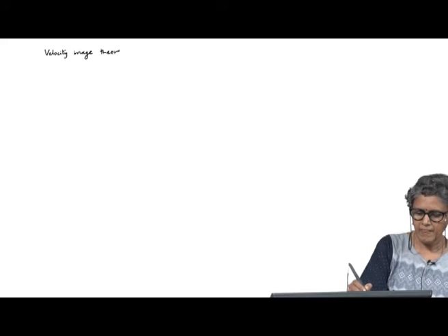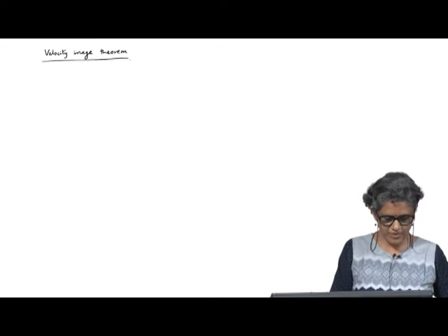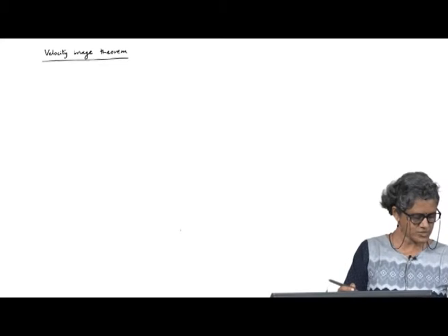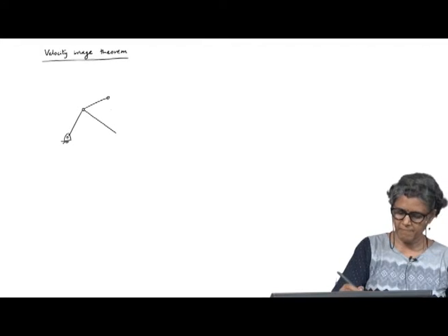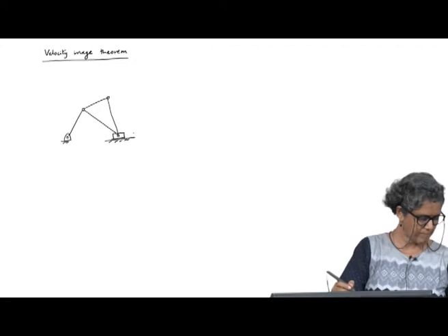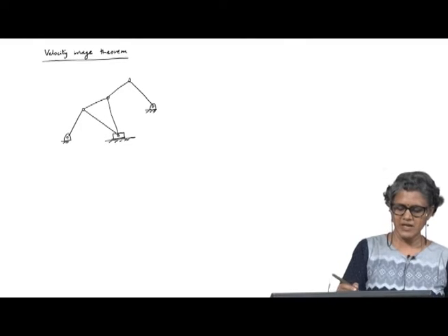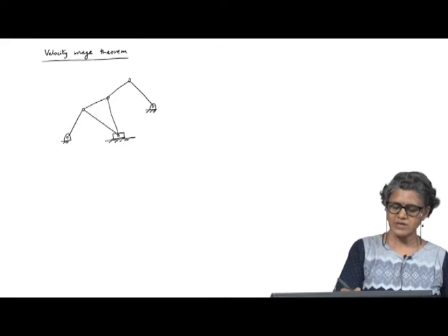So, when you are doing graphical analysis of mechanisms other than a 4 bar, for instance, if you have a mechanism like this, a 6 bar, where another dyad is driven by a coupler point of the, okay, in this case it is a slider crank, but I could technically have a 4 bar also.